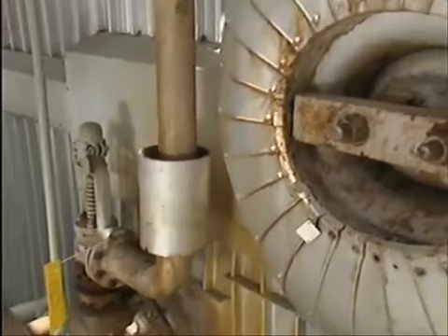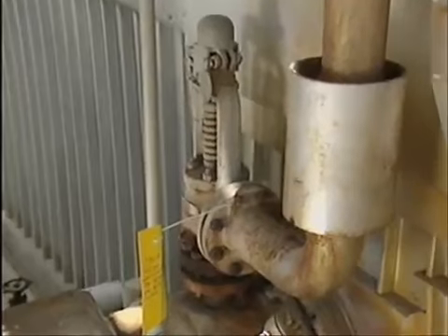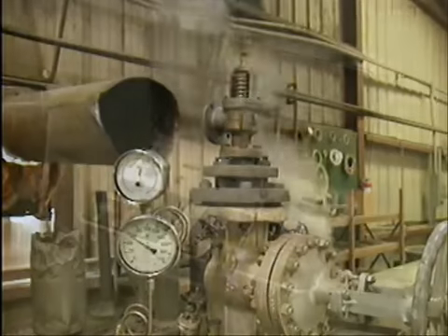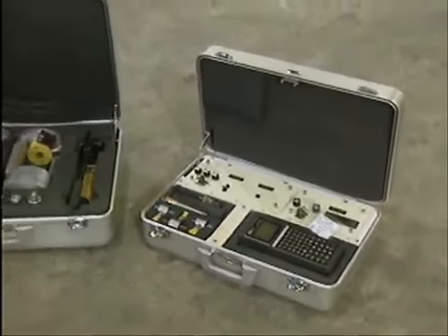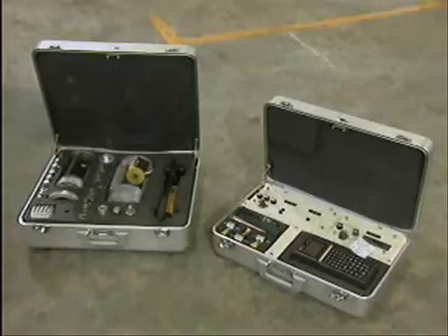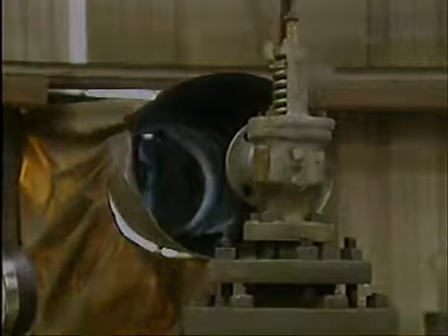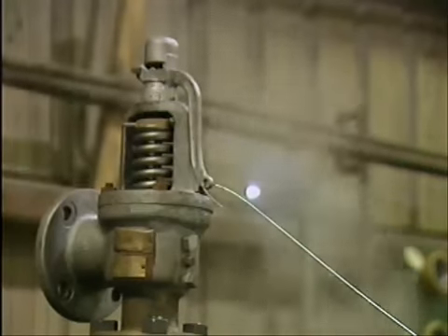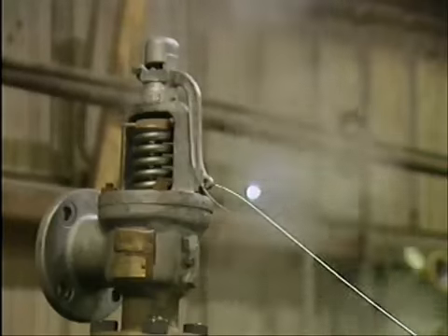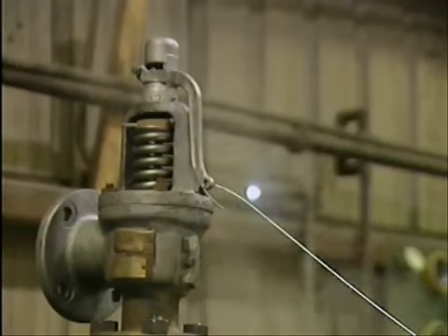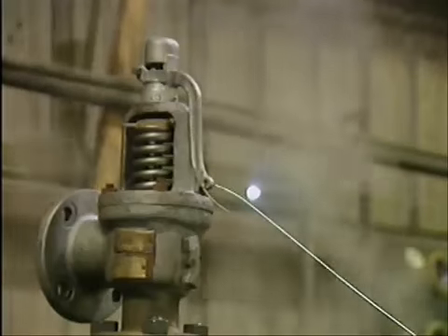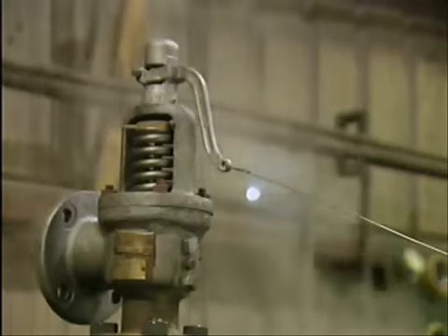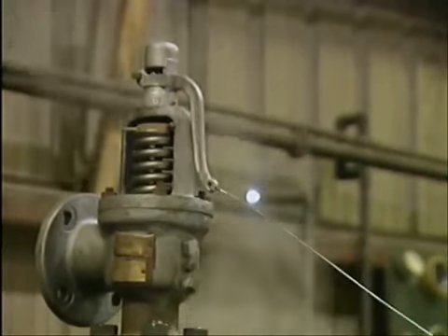Safety valve testing typically includes testing popping pressure. Popping pressure can be tested either by raising system pressure or by using an auxiliary device such as a hydraulic jack to lift the stem. If you use system pressure to test the valve, you should first lift the valve by hand to warm it. This helps ensure that the metal parts of the valve are at the same temperature before you start testing the valve to check its popping pressure. The parts will then expand and contract at the same rate during the test.